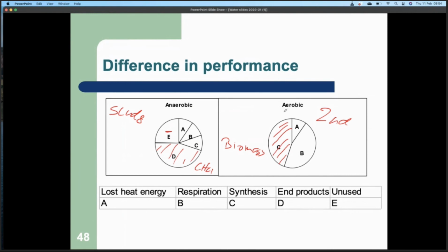So they still grow, build up biomass. So the biomass of the aerobic bacteria tends to not have all the stuff in it that we throw in the wastewater, because it's just biomass. So the biomass here is relatively free of all these inhibiting substances that we throw into the water. And that's why anaerobic bacteria can digest this biomass relatively easily, because it's not contaminated to the same extent as the original pure wastewater is.